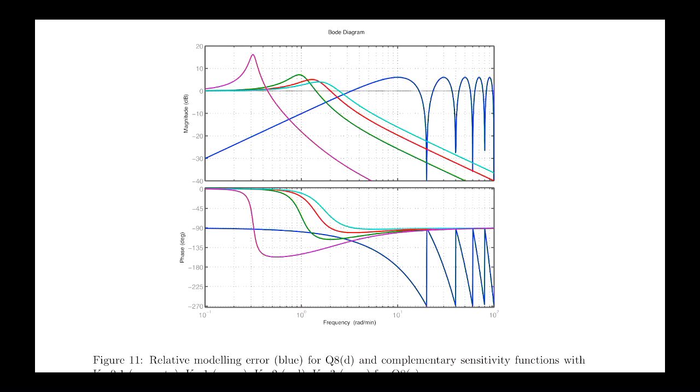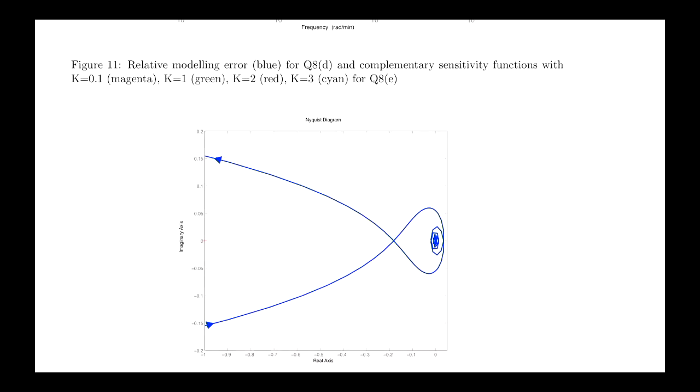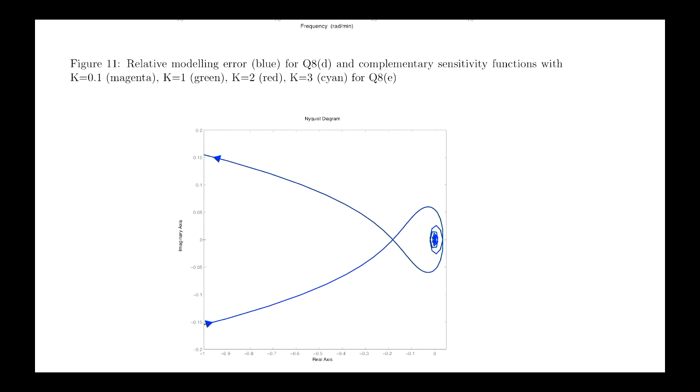Okay, and if you looked at the Nyquist plot, this is what the Nyquist plot looks like when you include the delay. Right, and so the Nyquist D contour that we're doing now has an indentation around the two poles at s equals 0.